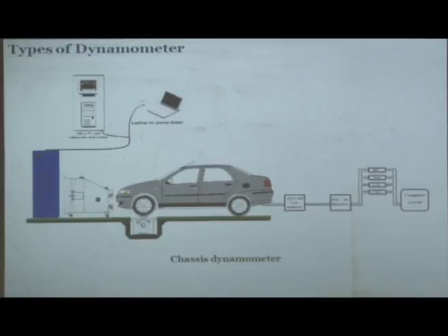And then of course you will take the exhaust gas, put it through the PM interface and measure the PM, and then you will measure the different regulated emissions using such an analyzer, and do whatever test you want to, but this is the heart of the system.